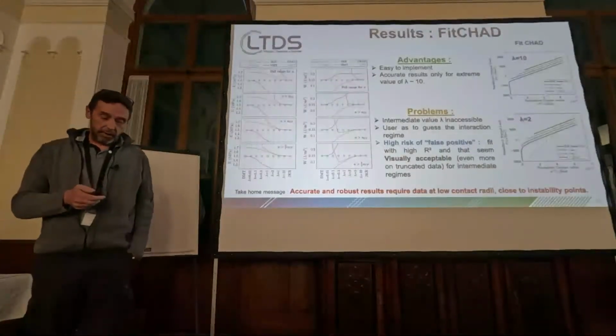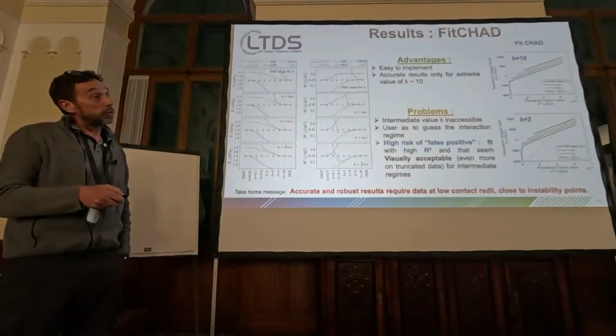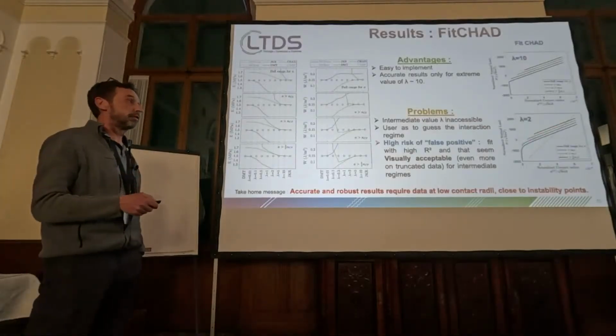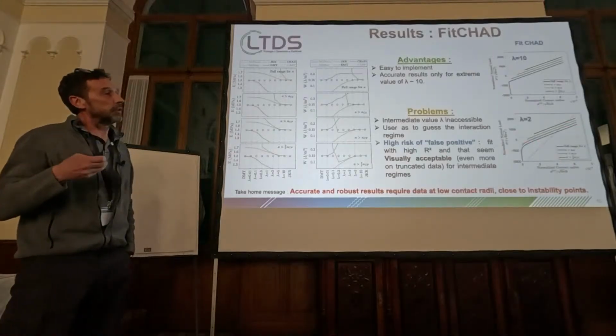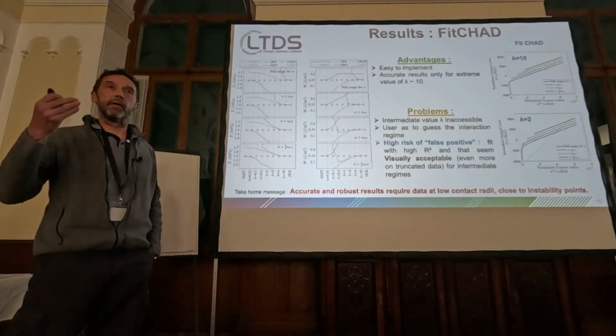So you really have to take care that your data go down to a very low contact radius, as close as possible to the instability point, because everything that will give you information on the adhesion regime is somewhere here at very low contact radius.